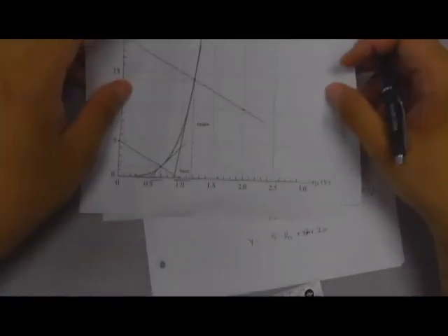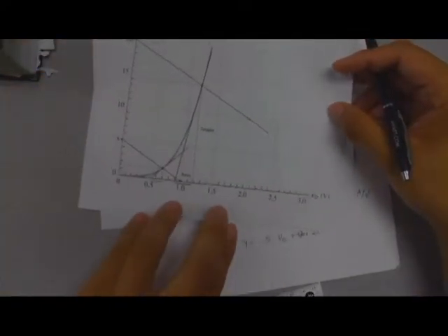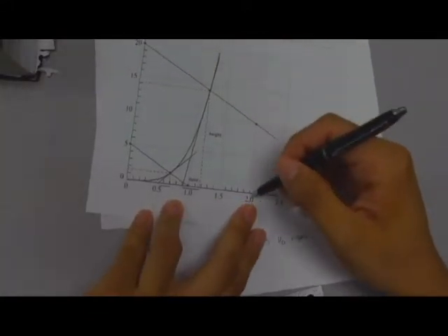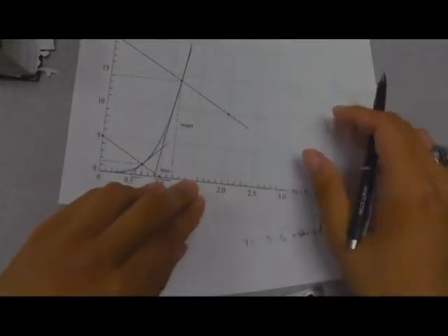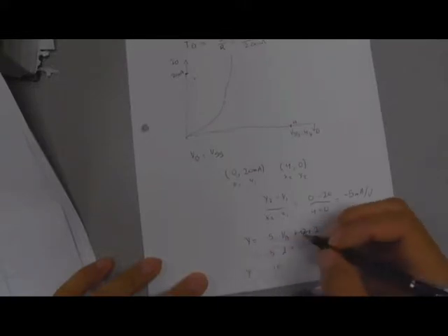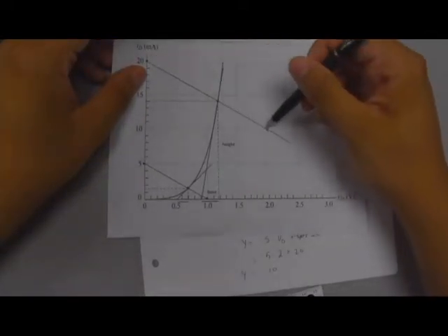Now, we can pick literally any point, but since we want to actually cross the load line, he picked just this point along the line. So if we pick VD equal to 2, we'll see that y is equal to 10. So negative 5 times 2 plus 20 is equal to 10. So that's why he was able to draw this line here.